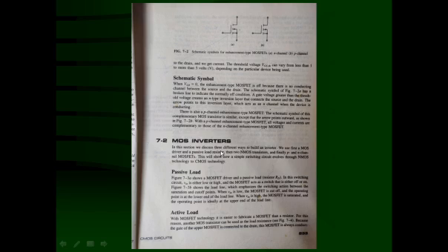So one way to prepare a MOS technology or MOSFET inverter is with the MOSFET as the active device and a passive load resistance, just like RL. Here it is named RD. Then the second way uses two NMOS transistors, which is called active load.